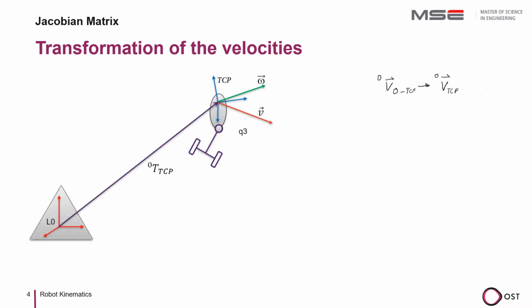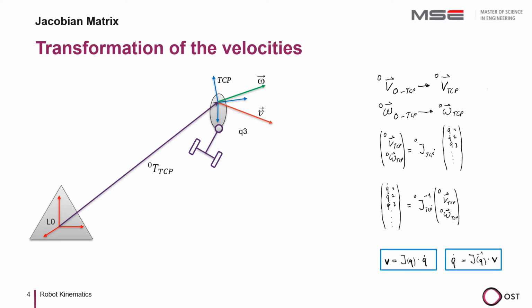While the forward and backward kinematics of robot arms and mobile robots differ, there are no formal differences in the transformations of the velocities. For mobile robots, the derived generalized robot coordinates are the wheel movements and the movements of any actuators on the robot.